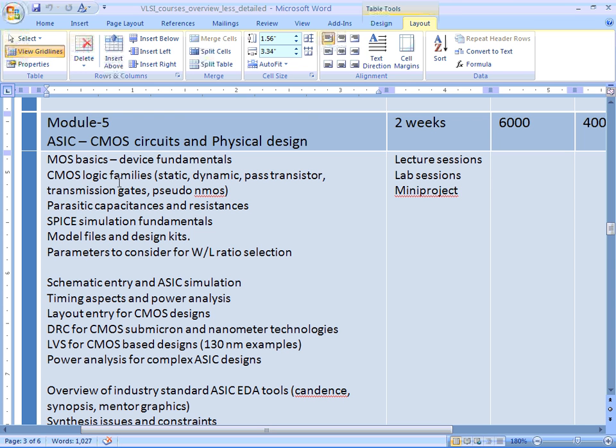And today, let me tell you, in industry the jobs are not clearly bounded like that, this is verification, this guy is design. It's not that. When you are doing verification and you notice several bugs, and the cause of a bug is very clear, then you have to fix the bug also. Got it? An example is something like this: as I said, in control and data path design, enable is going to all of them, but you notice that in one place enable is not going. That's a bug. As per the design spec, enable should go to all the flip-flops in the design.